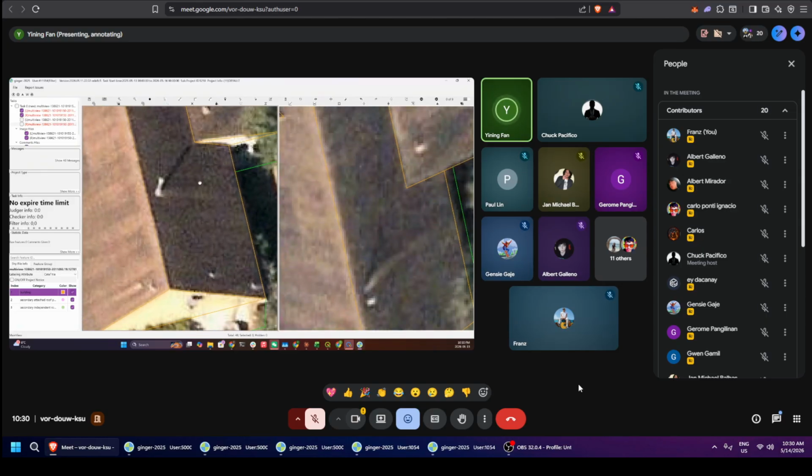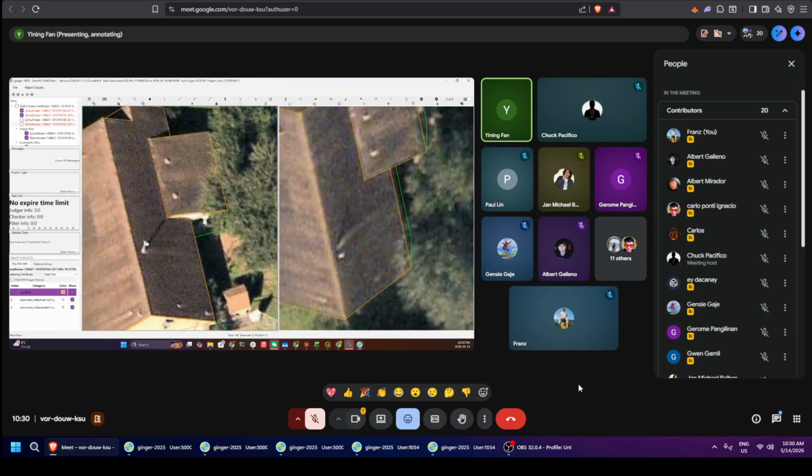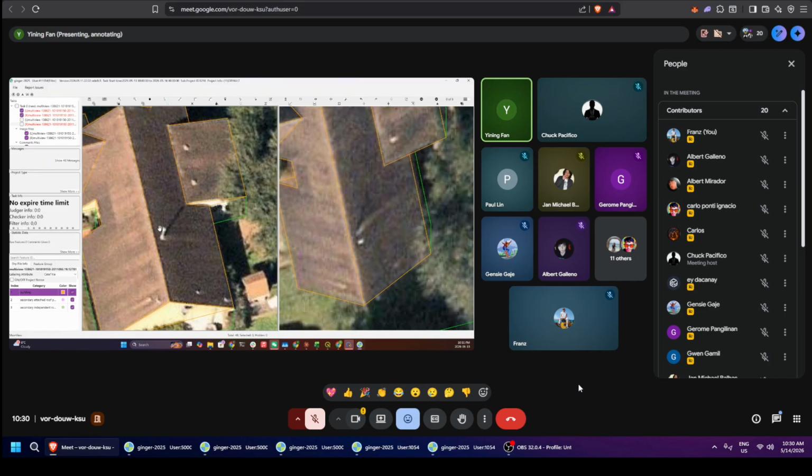And also, for example, let's just say right here you have a roof geometry, right? But you assume this is a chimney. As I mentioned before, the chimney needs to be included. So for here, we can just draw a little square. Let's make it parallel to the stage. So need to change the title. And on the other side, match the height. Select the same, move it to the correct location right here. And on this side, just drag it all the way down. And you will have your roof. You will have your chimney.